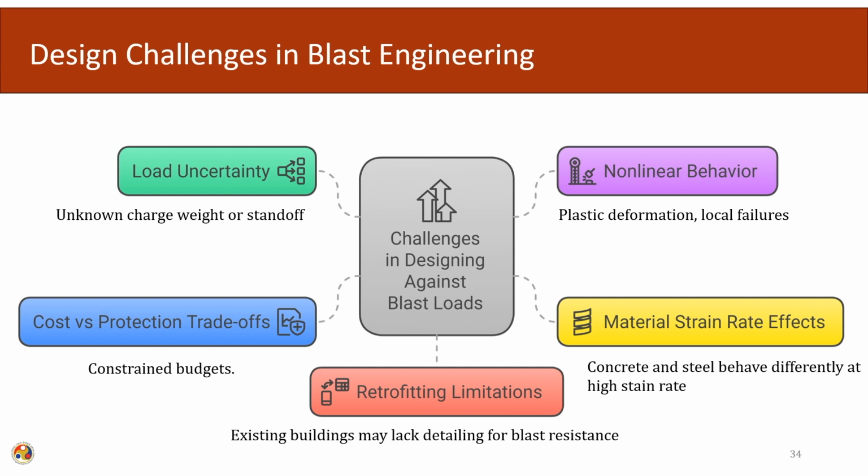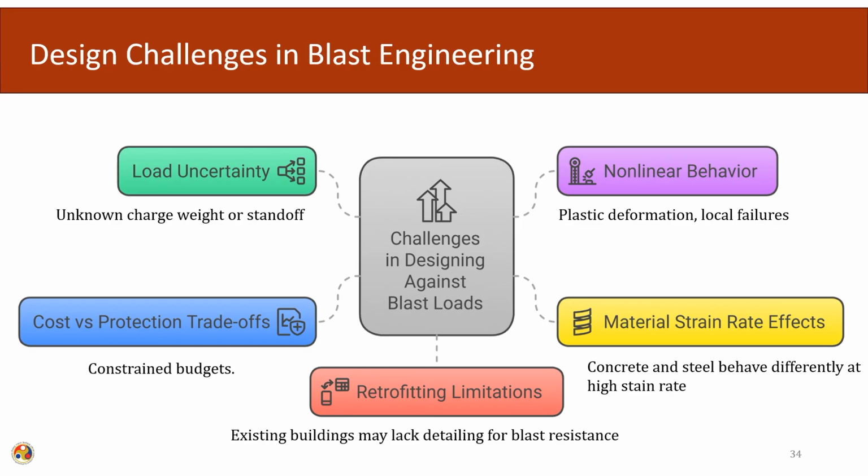So again, depending upon the cost, we have retrofitting limitations. There might be two cases. We have an existing building which we need to retrofit against any blast threat, and it might itself have some limitations due to the amount of detailing that has already gone into the existing building. Or we might face a scenario in which a newly designed building has been destroyed by an event that we have not designed for. The event was more than the expected event and we need to retrofit that structure. So again, the cost versus protection trade-off comes into the picture.